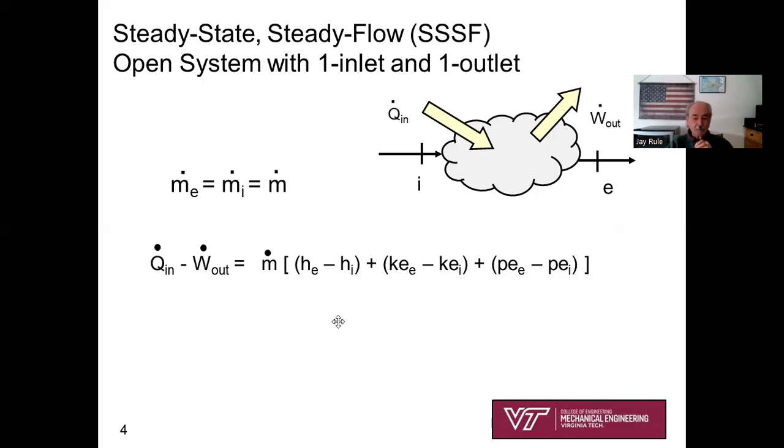It is my hope that you have this nailed in your head so that you don't have to waste time in a time situation, going into a formula sheet or fishing through notes or however you're allowed to do. Don't waste time on that. Have this in your head, because by and away, the most frequently occurring problem for an open system is going to be steady state, steady flow, one inlet, one outlet. Hope that helps you simplify things in your mind.